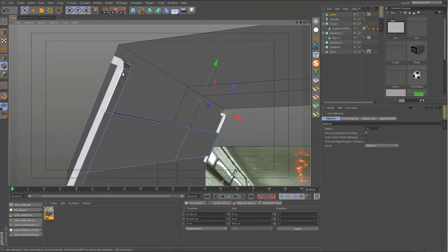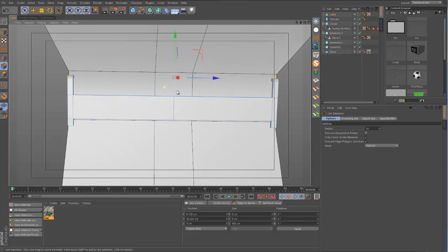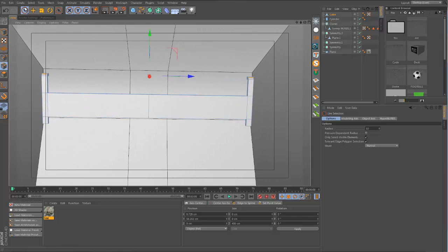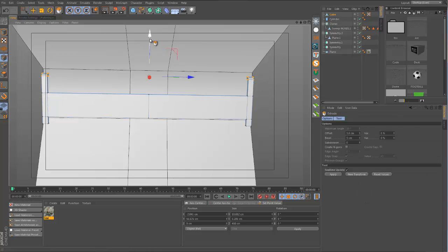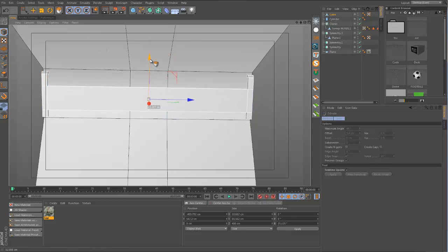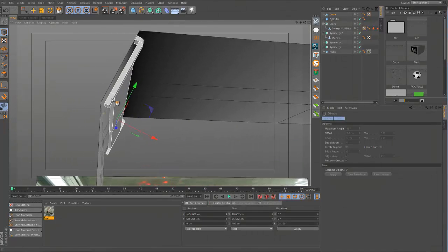Okay, I went too far with this. This is way too high now. So what I'm going to do is look from this direction, go to rectangle selection, go to point mode. Only select visible elements is not ticked, so I can get all of these points and just move them down a little bit, and then get the whole block and move it up just like that.